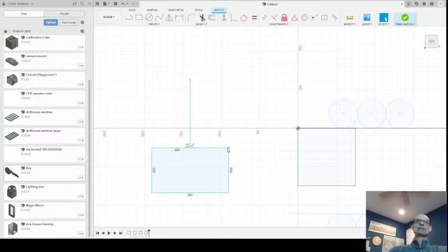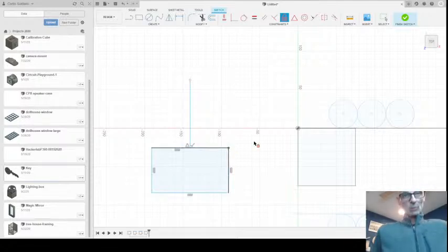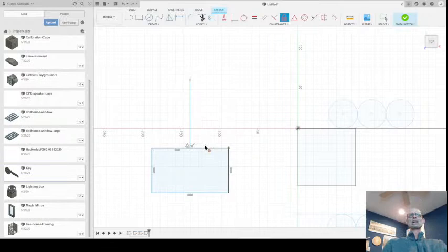We're going to do this here. I want to fix, trying to think this through. I want to fix. Yeah, no, I'm sorry. It only allows me to fix the thing I'm clicking on. So it fixed that point right there to where it's at, regardless of where it's at, because it didn't need any other anchor point. So then you see those two lines become black because now those are fully constrained. They can't be moved, scaled, or rotated.